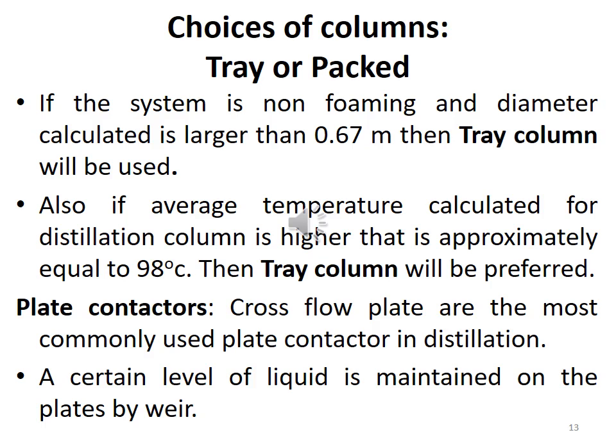And the plate contactors are actually the cross flow plates which are most commonly used as a plate contactor in the distillation. Contactor means the offering of a platform to provide an interaction between vapors and the liquid, in which liquid flows downward and vapor flows upward. In plate contactors, liquid usually flows downward and the vapor goes upward.